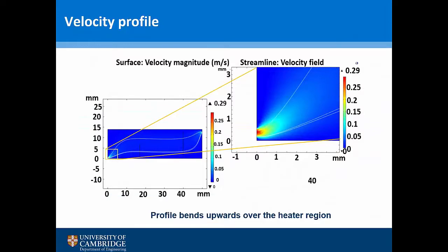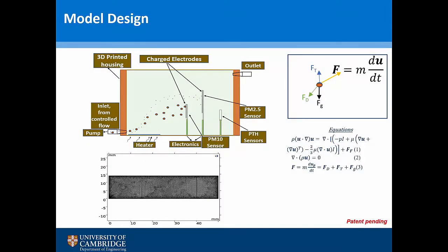So what are the results that we get? After simulating these, the simulation goes such that we first couple CFD and heat transfer to find the velocity, the pressure, and the temperature profile of the system, and then you couple that result with a particle tracing model. What that does is use the values of the velocity, pressure and temperature that you've gotten for all the points in the system, and then simulate again to get the particle trajectory at those specific points.